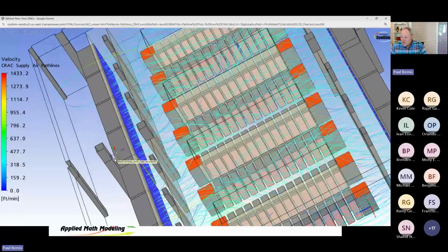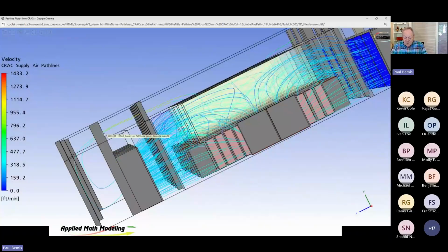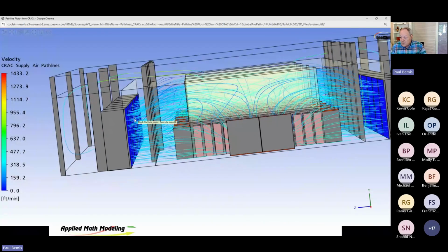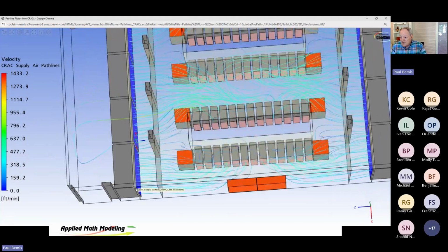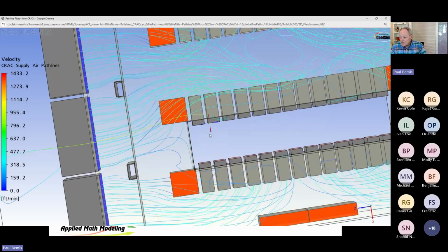I mean, this is in feet per minute. So again, sorry about the English numbers, American numbers really. But you can see here that the air is coming rushing in at fairly high velocity. And so what happens is, as that velocity comes rushing by around these corners, it's going to create lower pressure in this region. There's a lot of fast air coming in, which causes lower pressure right in this region right here. And this is your rack rail.